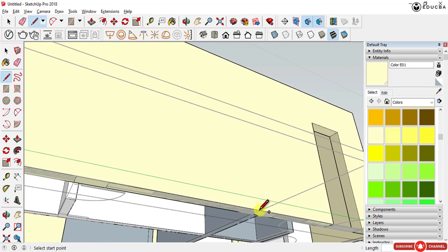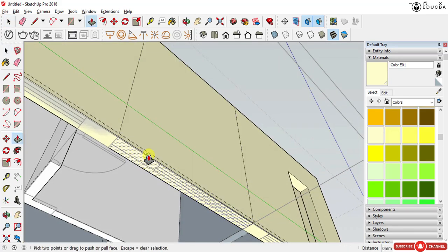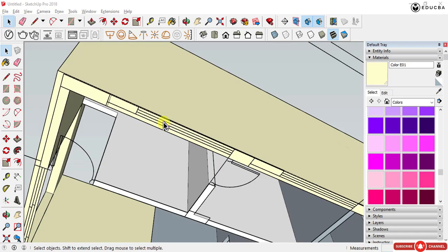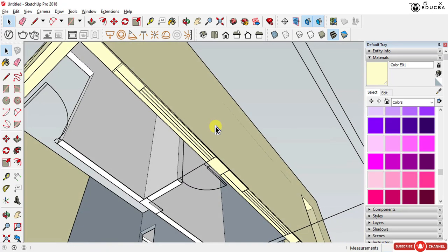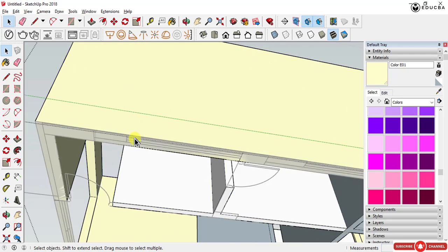Now what I can do is erase a line here, click, copy the same, bring it to the next point as it prompts me, and when I push this surface to 1000 mm. So now we can use another trick for making the low height windows. You can select the surface, select the internal surface and push with a control.